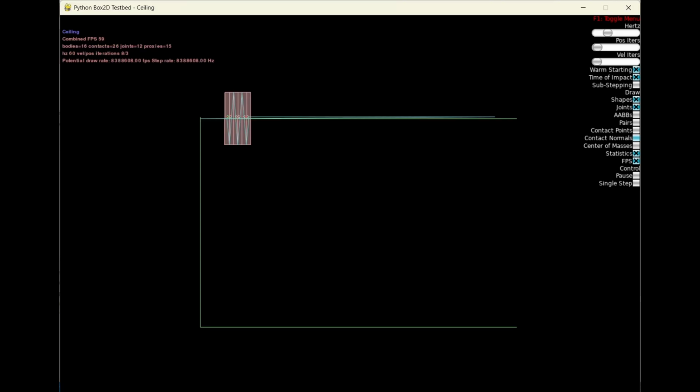Here's the simulation result when I moved the wheels closer to the middle. It has a much easier time flattening out the ceiling, but it still doesn't quite get to completely flat. I need it to be flat and flush because any gaps where the edges by the wall can't press up against the surface above it will let the sound come straight through. But the only way to get that flat is by adding a new vertical force to the system.